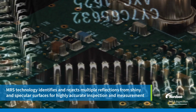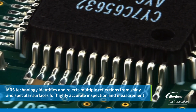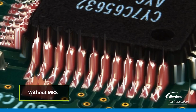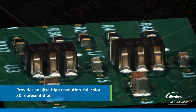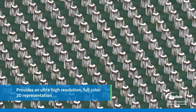Absolutely. Yeah. So what size are the 4 cameras that are around the edge? 25 megapixels, so you can kind of combine that as well. That's quite a lot of capacity. So this is our high-speed camera. We also have a high resolution, so we go from the 9-micron resolution to 7-micron resolution. So we still have that 30-millimeter range down to a 10-millimeter height range, so you're capable of rendering with it. And then it's on the Z-axis, so we can move that up and down and change that focus position.